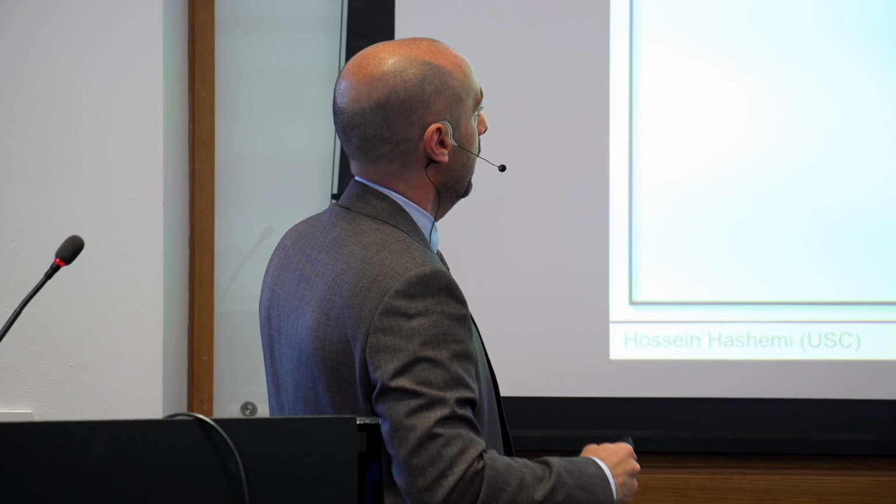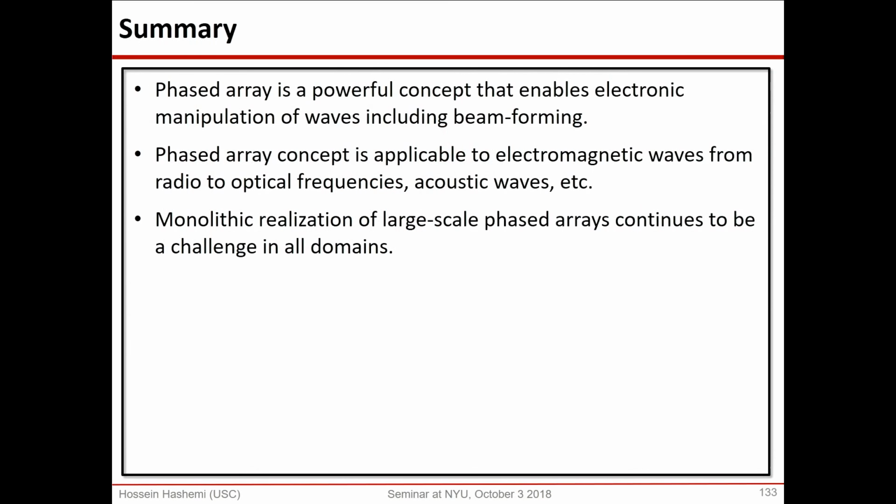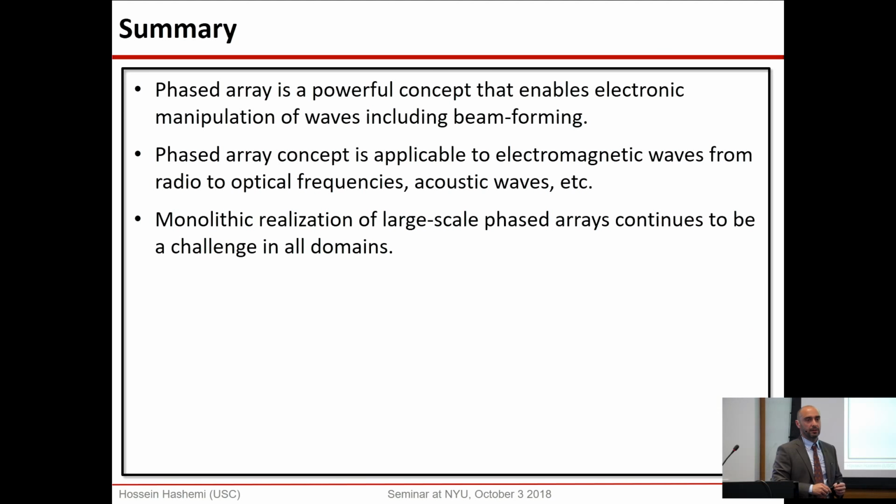In the summary of this talk, I think phased array in general, or interference, is a very powerful concept that enables manipulation of the near and far field. The phased array concept is applied not only to electromagnetic waves, radio and optical, but also acoustic waves. If you've ever taken an ultrasound, or if you know a relative who has taken ultrasound, all of these ultrasound systems use acoustic arrays to try to find things inside your body, including the babies.